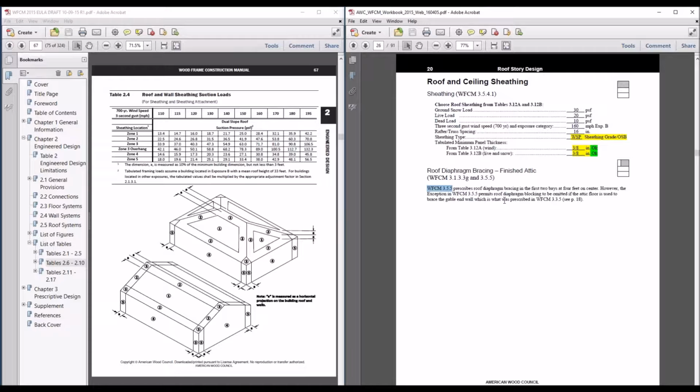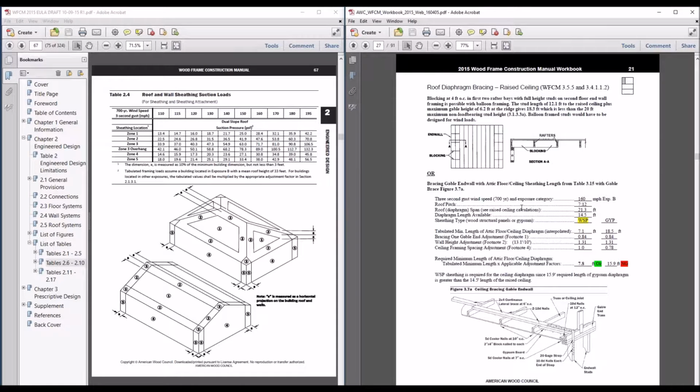If you just had a ceiling system you might need to block the rafters, but we've actually blocked, at least on this end of the building, the end that's got the attic space, the floor system, so we don't need blocking in the rafters. You'll see in a second how we design that vaulted ceiling, the ceiling joist, as an alternate to blocking the rafters. So just stay tuned and we'll get there in just a second.